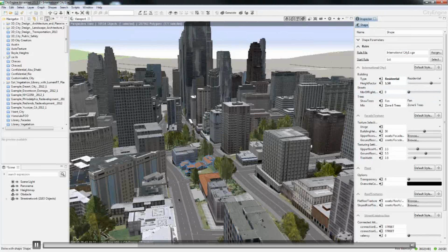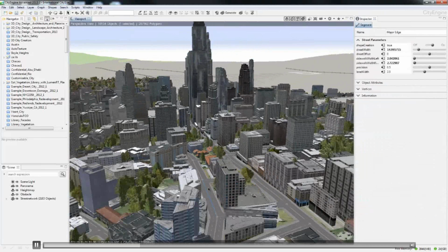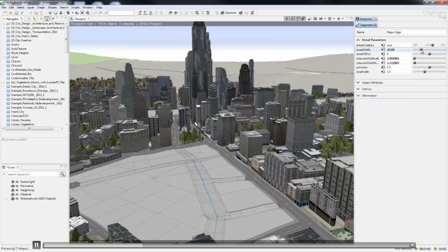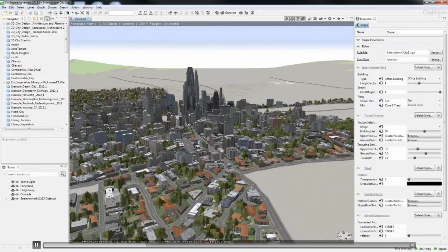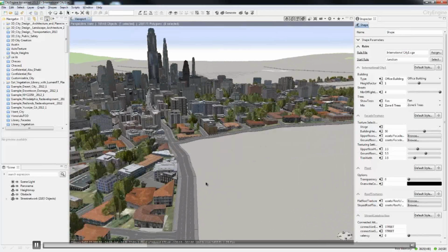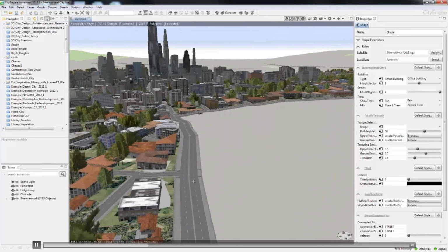The magic happens in the inspector, and you can modify almost any value or variable, making the geometries align to what you want them to look like for a specific city or specific area. And you can even select streets, change the street widths, edit things on the fly, and everything adapts to these changes with these dynamic layouts. And then not only that, we can also do editing or creation of GIS data and information inside of CityEngine.